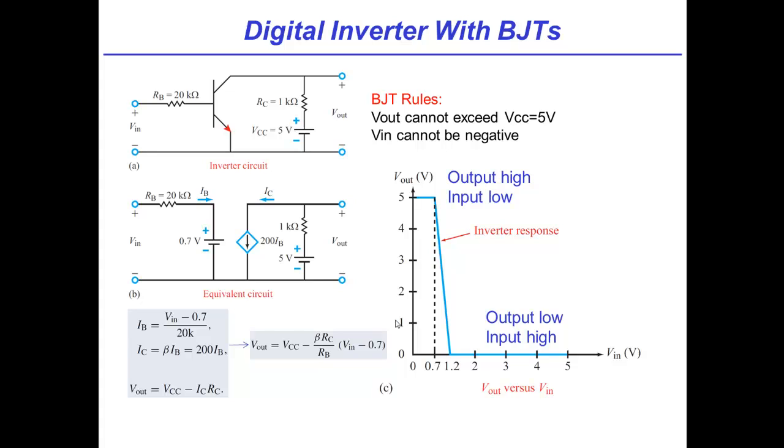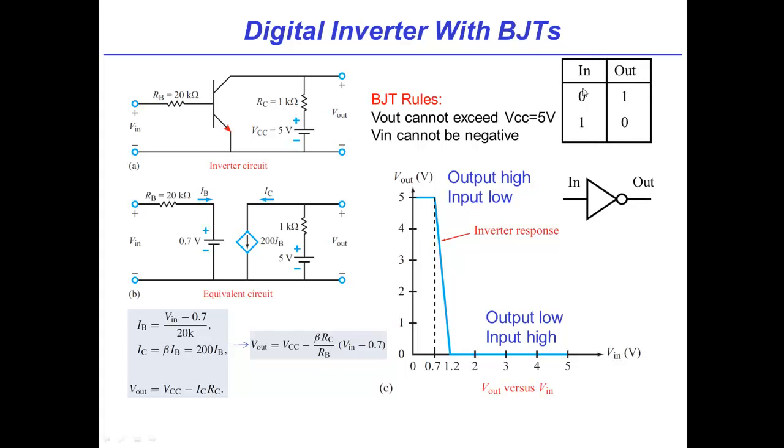Inversion basically says if you have a binary system with two possible states, 0 and 1, an inverter will take an input of 0 and produce an output of 1, or take an input of 1 and produce an output of 0. We represent inverters by this schematic, which you've probably seen before. So in fact, you've now built an inverter. Let me guess a couple things. One is, my guess is that you could probably build more complex logic gates than this with BJTs, obviously. That's right. And that's probably what people were doing in the late 70s, early 80s, right? That's right, with the early Intel process.